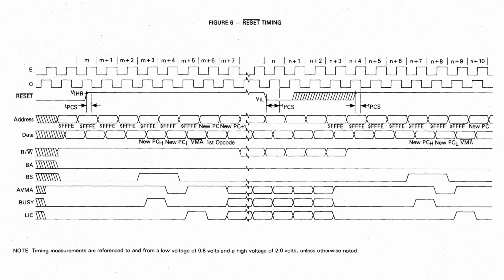The reset signal performs a critical system function. It initializes anything that's watching it to a known state. In the case of the 6809, it also causes the CPU to fetch an address from a well-known location called the reset vector. It loads that value into the program counter and then begins executing code at that address. The reset signal on the 6809 is an active low signal. The CPU is then held in reset until the signal's rising edge, which then begins an 8-cycle process to bring the CPU out of reset and begin executing code.